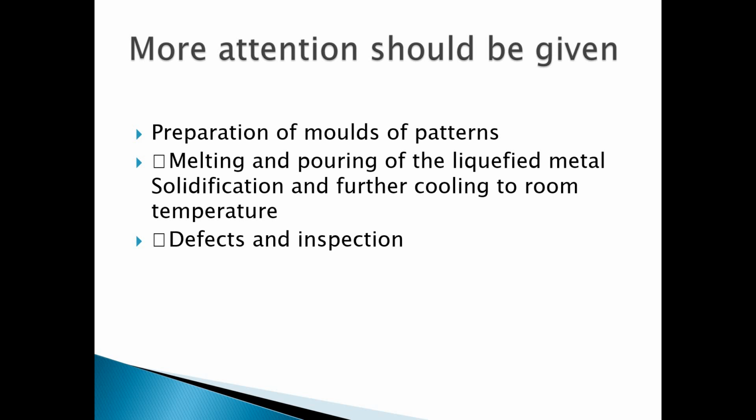Second, melting and pouring of the liquefied metal, solidification and further cooling to room temperature. One more important thing we need to attend to is melting of your metal. Your metal must be completely liquefied, and the liquefied metal must be filled into the mold as early as possible. Once you have filled the mold, we need to wait for cooling.